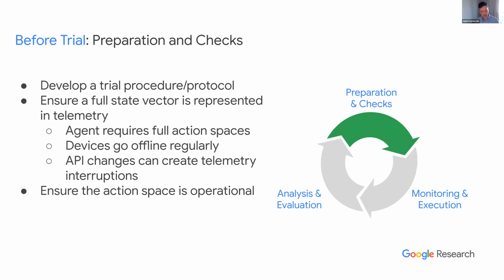So one needs to make sure also the action space is operational, and this is a little bit challenging. You can imagine that you bring the agent up online and you just observe the state and make sure all the devices are fully represented. But you also need to make sure that before you hand control over from the baseline, from the existing control to the agent control, that the agent actually can assign values to the correct set points.